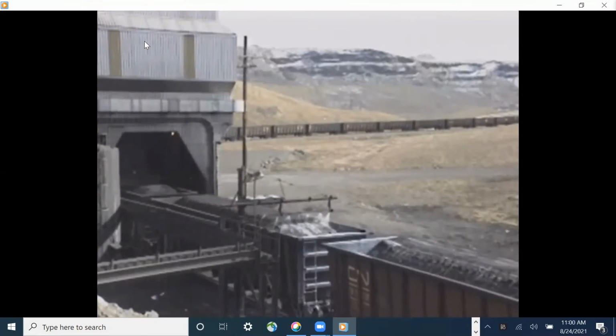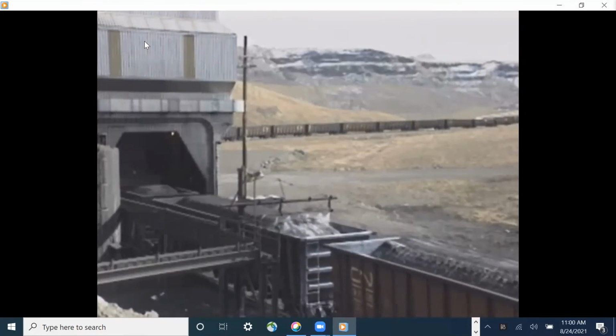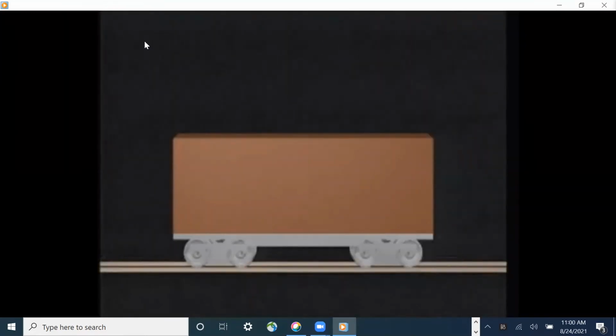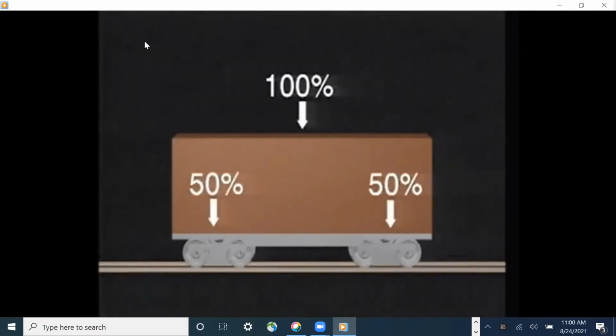Vehicle weight produces the most significant vertical wheel load, simply a measure of the static weight of each car and its contents, divided among the various wheels. However, when a rail car rolls along the track, rocking, bouncing, and other dynamic actions or reactions change the value and position of the vertical force of each wheel on the rail head.